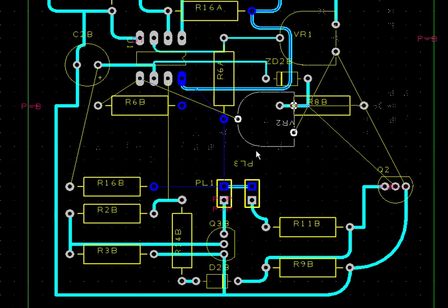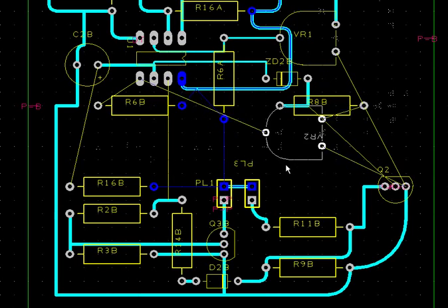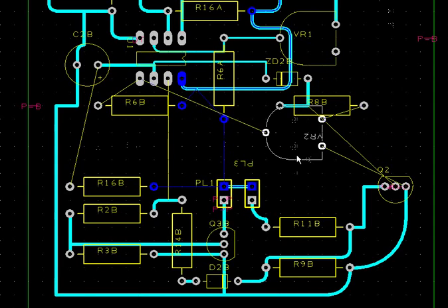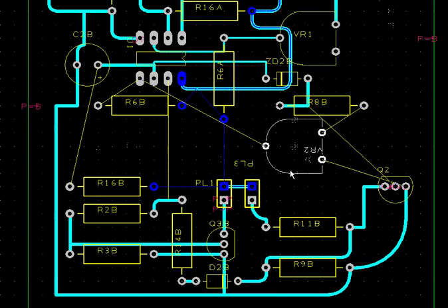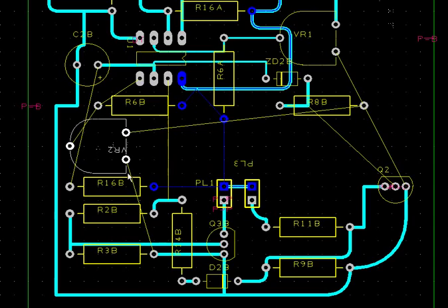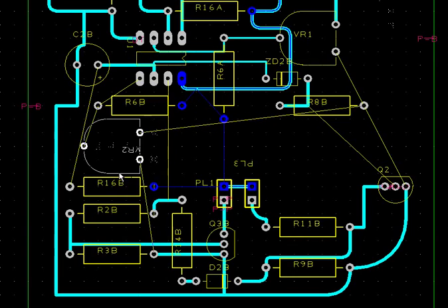And when the nets cross, for example here, when these lines cross, it means that you can't get a direct path because the circuit's blocked. But when you get it in the right position, you can take a track through. The line can go behind certain resistors. So in some situations you can actually get access where the track can go behind a resistor. Now we can't get to that one there because there's another track there which is blocking it.